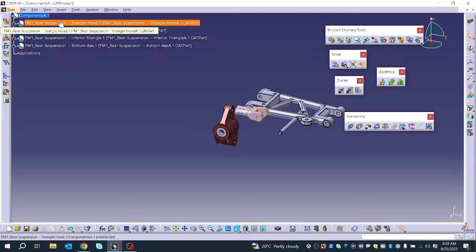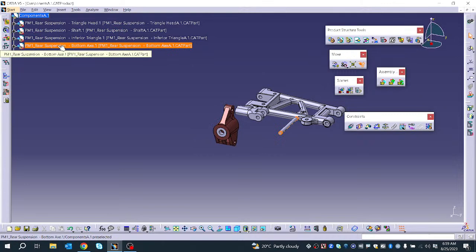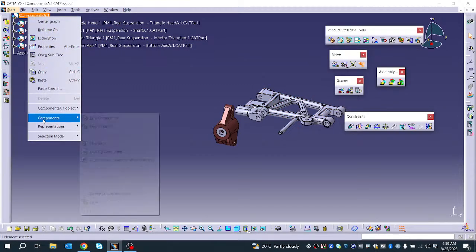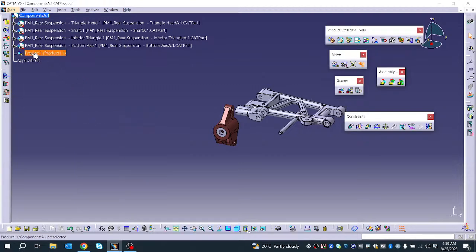Then the assembly document also contains a specification tree which shows all the instances of the parts and the sub assemblies. A blank sheet component icon means that the component is linked to an external file. You can see the blank sheet over there. If I add a component, you cannot see this blank sheet. If the blank sheet is there, then it is linked with an external file. For example, all the components have an external file like CATProduct and CATPart.